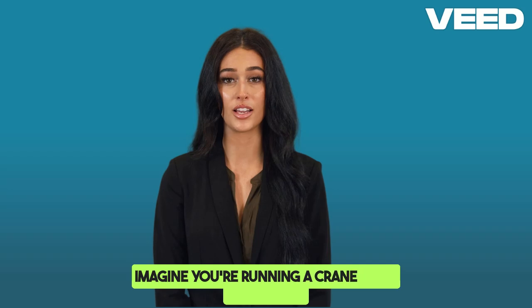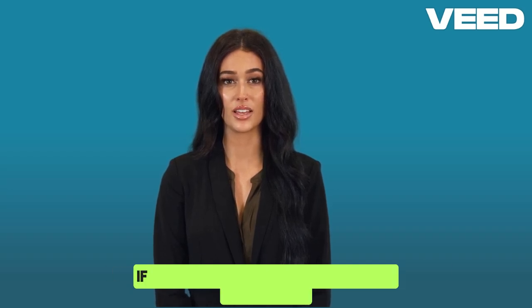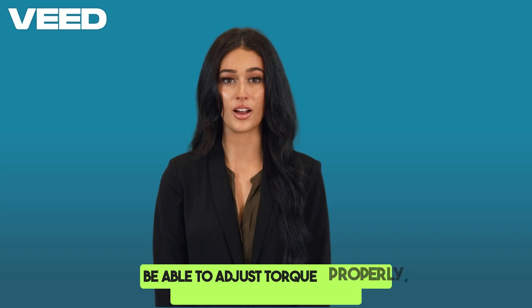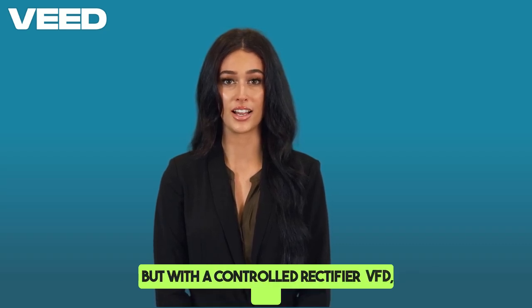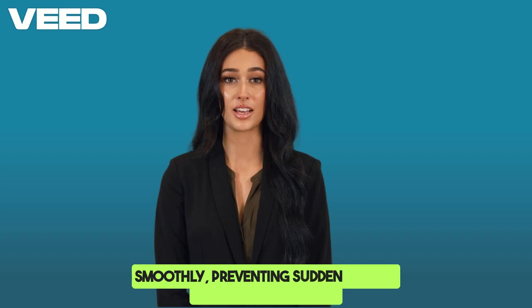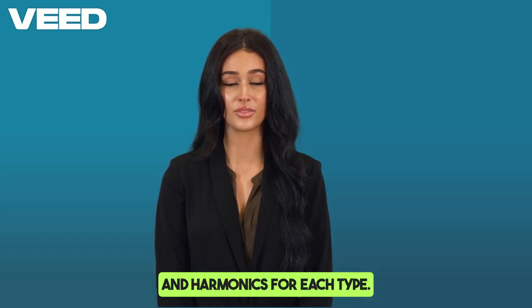Imagine you're running a crane hoist motor that needs precise torque control at low speeds. If you use an uncontrolled rectifier VFD, it won't be able to adjust torque properly, causing jerky movements. But with a controlled rectifier VFD, the motor speed and torque can be adjusted smoothly, preventing sudden shocks and ensuring safety. Now let's talk about power factor and harmonics for each type.